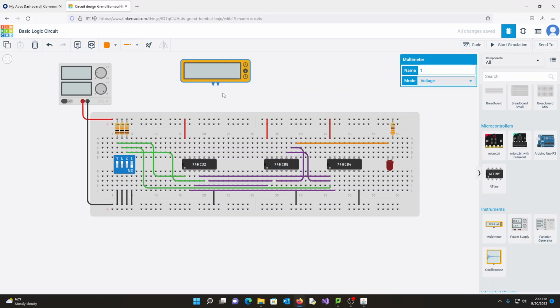So basically, if your design's not working, then obviously you want to check all the wiring and that stuff. But you can find whichever combination's not working and start tracing using the multimeter. You can start probing the individual pins of the ICs and see if that makes sense.